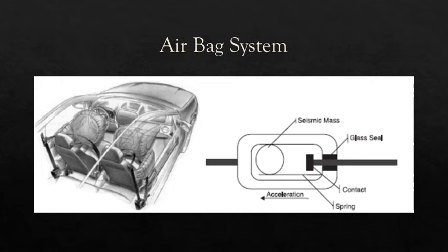The system consists of two portions, the crash sensor and the inflation mechanism. Crash sensors or acceleration sensors are mainly used to achieve airbag release in the event of a crash. In the event of a crash, these sensors detect the impact and inflate an airbag which is in the steering wheel for the driver and in the dashboard for the co-driver.